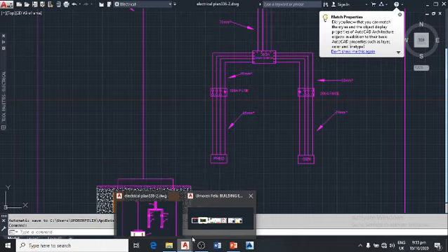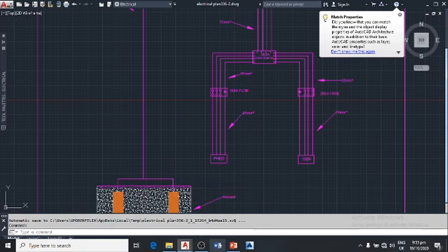So if our supply voltage is about 230 volts, for example, and we have about 121 kilowatts of electricity, by the time you divide 121 kilowatts by our supply voltage, let's say we are using 230 volts, we're having about 500 amperes.